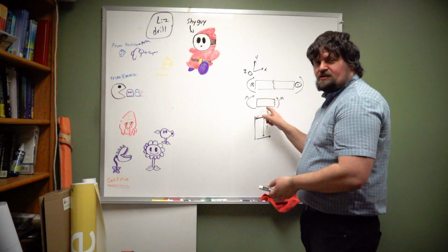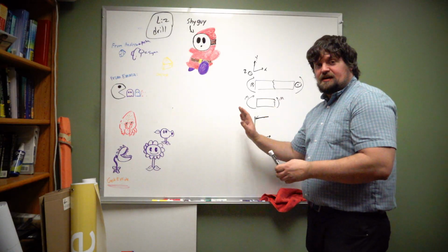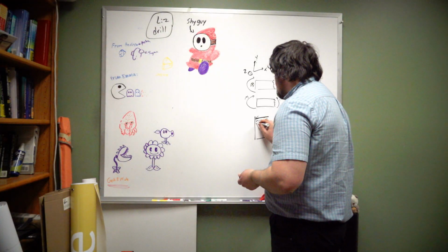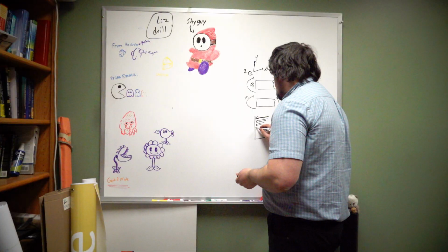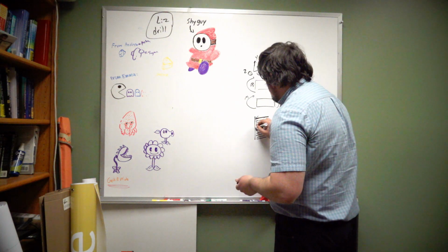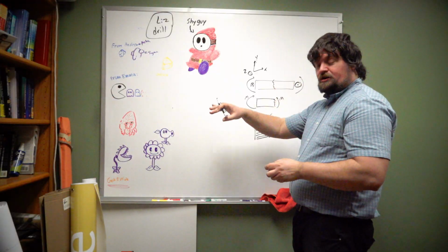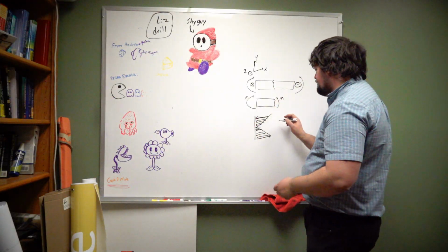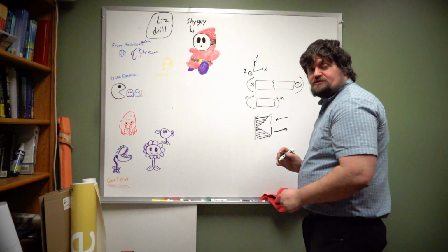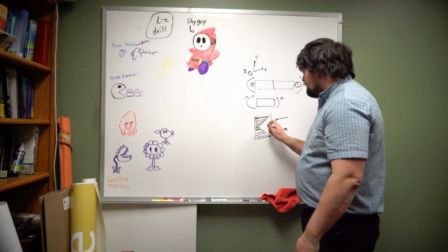Now, it isn't just going to be that we only carry load on the top and the bottom. It turns out that if you look at the actual profile, unlike the axial loading where it was constant across the entire interface, this one's actually going to decrease in value until it reaches 0, and then it's going to switch back the other way. And so you get this triangular trajectory for all of your loads, where all the ones on top are going in and all the ones going down are coming out. And if you sum all of these, you get a net force in that direction, and if you sum all of these, you get a net force in this direction, and then the total moment is going to be the difference between these two.